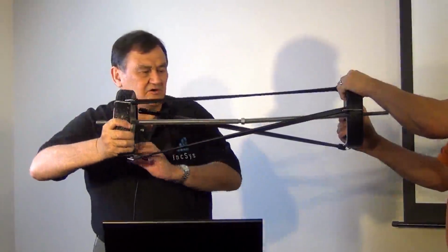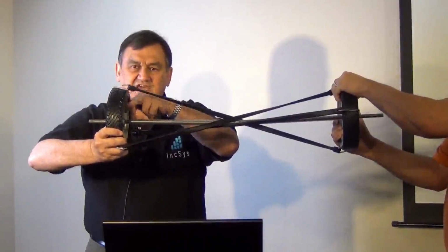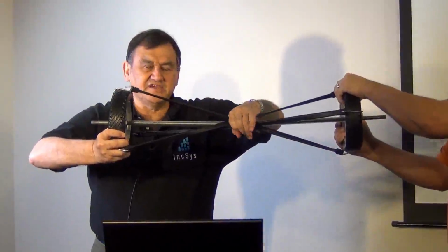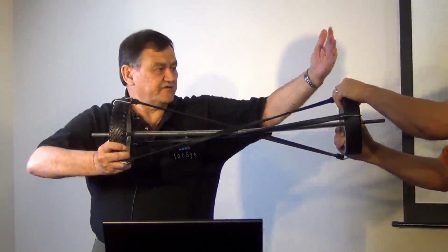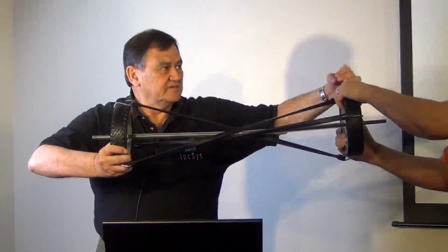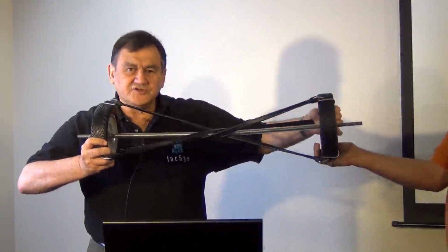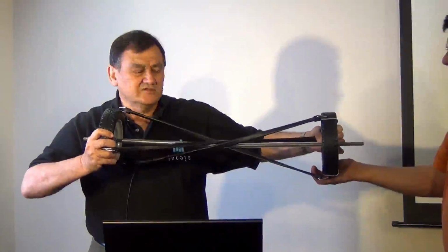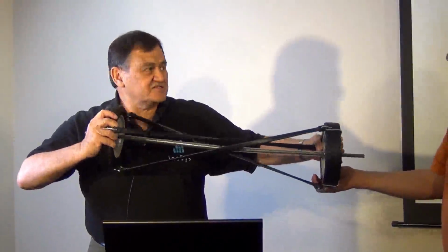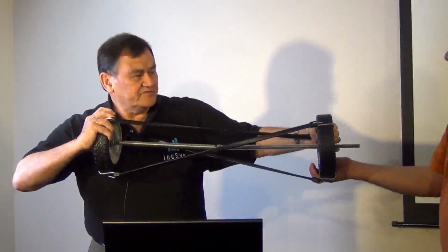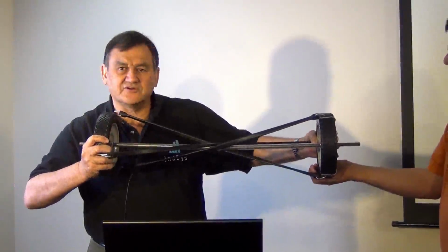As I advance my angle all the way to 180 degrees, I've got a fixed voltage, say of 500 kV here, a 0 voltage here. I'm going to have a huge current flowing in this direction. At this point, I've got 500 kV, but it's out of phase. But again, I have huge current flowing in this direction. So those huge currents actually absorb VARs. The current drawn by that line is I squared times X. So that's the big difference to understand, is that that line can be a huge consumer of megavars when it is 180 degrees out of phase.